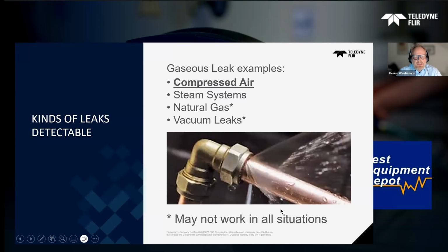It's very important to remember that a leak may not produce enough noise to be distinguishable from the background noise. In every production, you have kind of noise of running machines, etc. And normally when you detect leaks by noise, you have to turn off the systems. And with an ultrasound solution, you can do this during the running production.